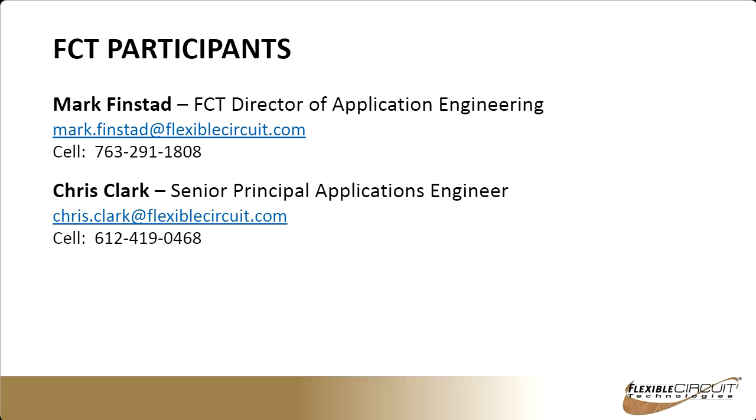Another question here is about the size and cost concerns in automotive battery heating. They're very large and cost sensitive. Isn't that difficult? It's not difficult, but it can be expensive. That's one of those things where we'd look at the object that you're trying to heat, in this case a battery. We have done battery heaters in the past, and in certain cases, to keep the cost down, you may heat just one side of the battery and then insulate that side so that you keep as much of your energy going into the battery as possible. Or you use multiple heaters to keep the heater smaller, so you don't have one large heater wrapping all the way around. You could have two smaller heaters that would cost a lot less.